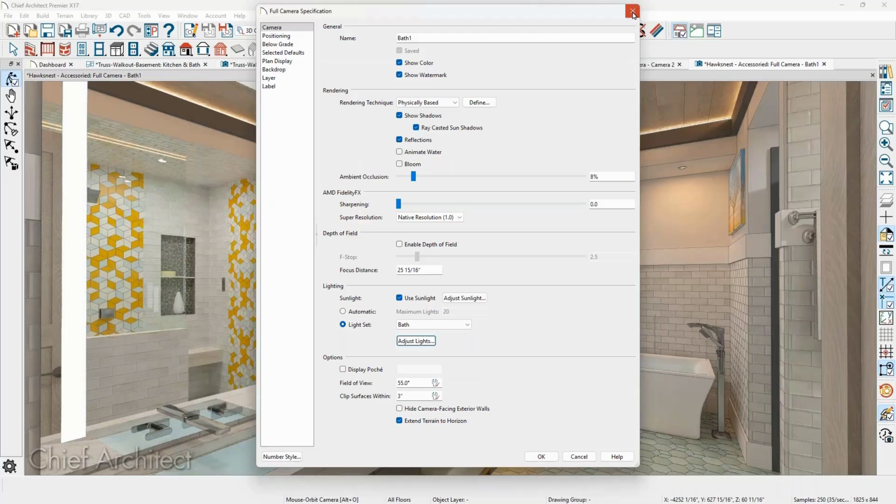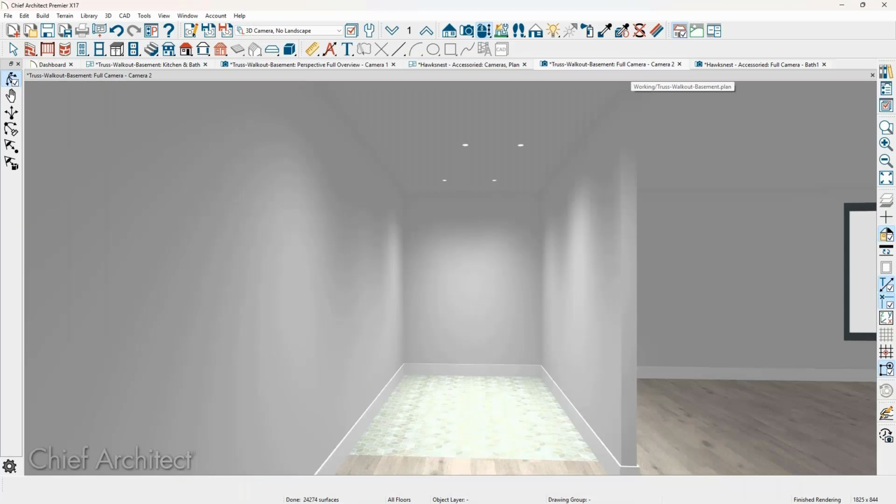When you have a very simple camera view that only has a few lights on it, you probably don't ever have to worry about that, because if you're talking about half a dozen lights, I think the default is 20 lights. But if you are seeing that, create a light set and then go in and turn on the specific lights that you want for your room scene. Sounds great. I appreciate it. Thanks.